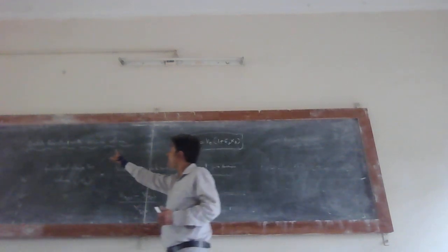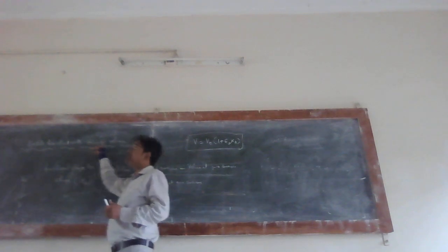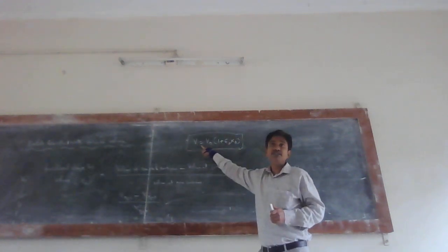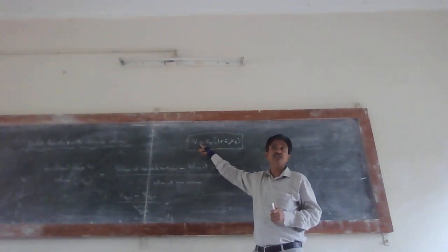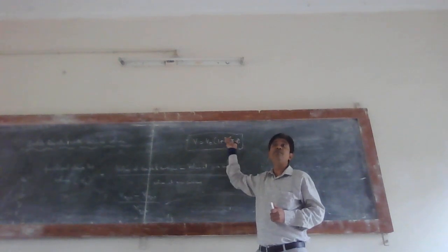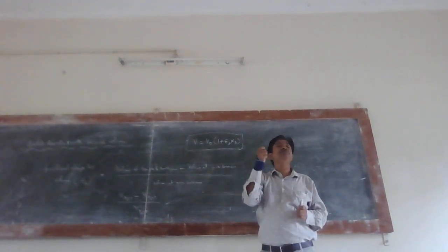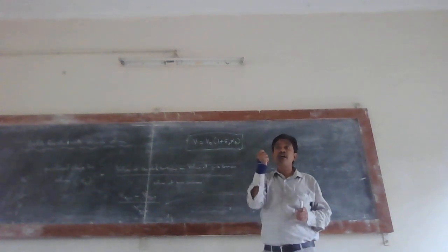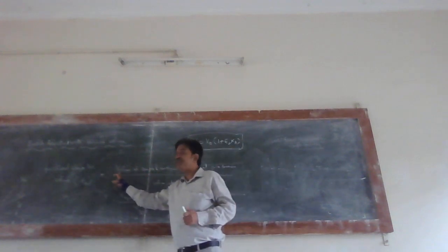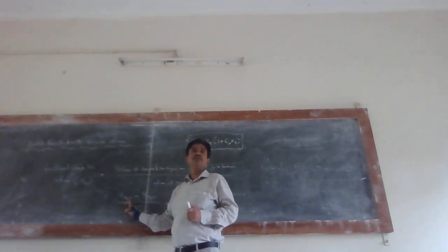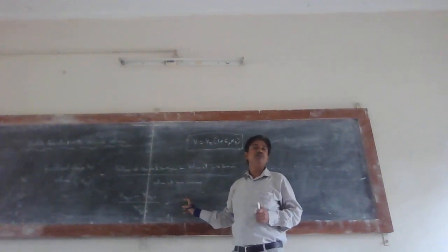Now we are studying the varying volume case. Now your volume will change. It will change with the initial volume multiplied by this term: V equals V0 into 1 plus epsilon A XA. Now that epsilon A is called the fractional change in the volume. How do we define it? Volume at 100% conversion minus volume at 0% conversion.